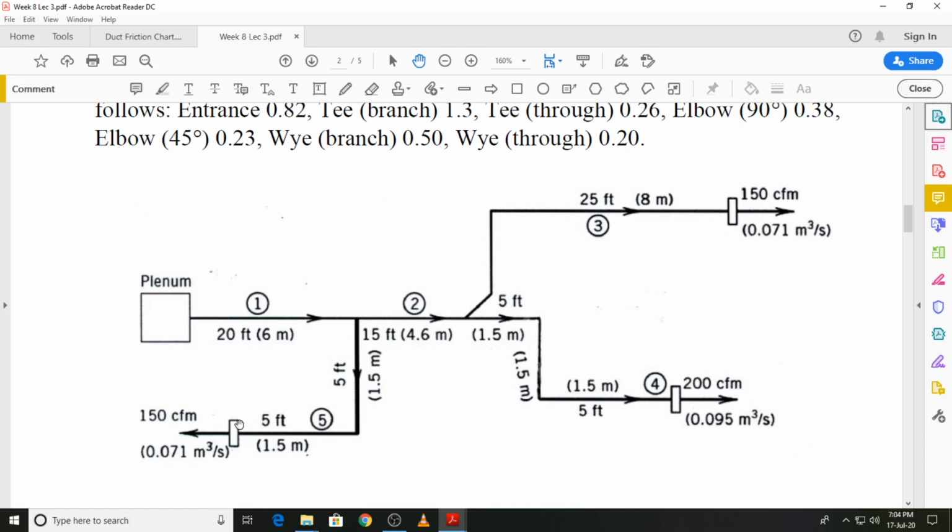I will now move on to that equation that we have to start with. Make sure you first write the full algebraic equation and then substitute the numerical values. Do not substitute the numerical values first. The algebraic equation tells us how well you have understood the process for calculating these pressure drops, and you might also have the advantage that some of those pressure drops might be required again. So if you have calculated them separately, you don't have to repeat those calculations again.